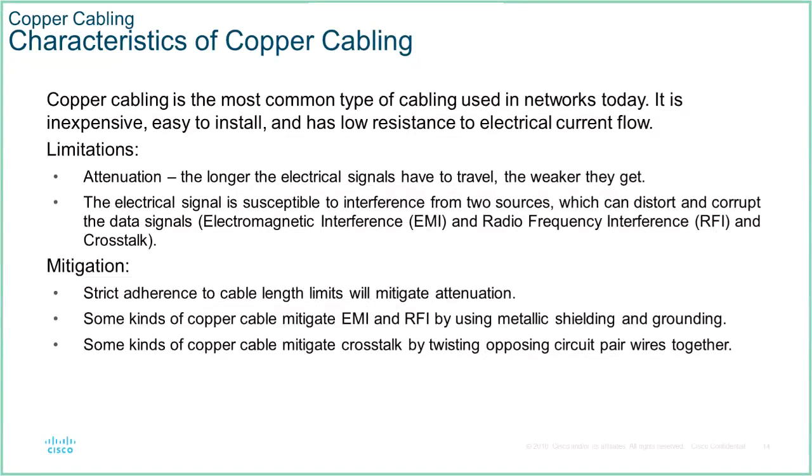Crosstalk, one of the main ways we get around crosstalk in cables now is: category 3 cables, they were just bundled together. There was nothing special about it, i.e. your standard telephone cable. Your category 5 and category 6 cables now twist pairs together at a different rate of twist per meter, and that stops the magnetic fields from interfering with each other because they wrap around each other.